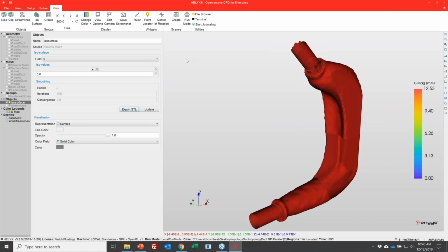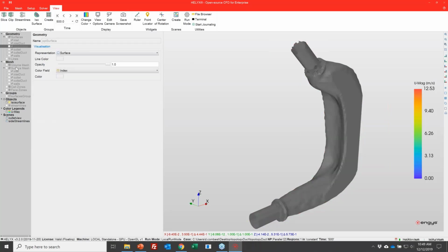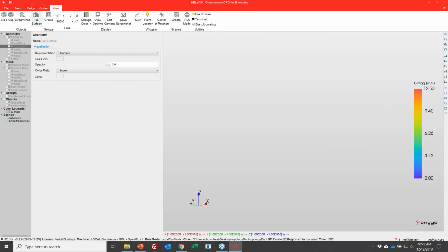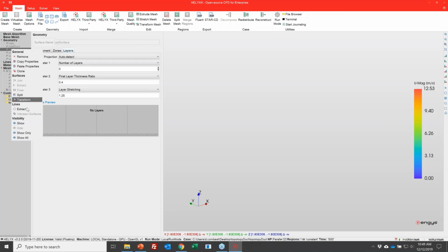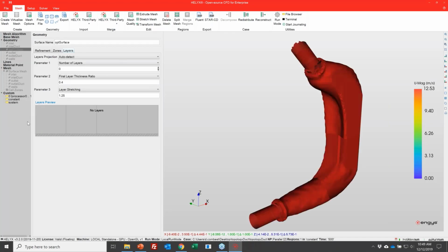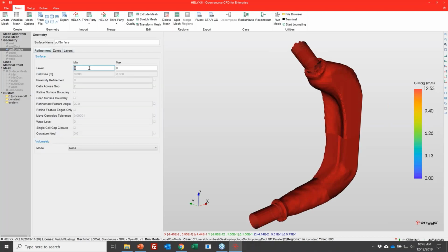There's several other parts of this whole process. One of the parts would be to bring this back in. So for this case, I've already brought it back in, but it hasn't been meshed. What we would do is we go all the way back to the meshing part, and we would re-import our optimal surface. There we would probably increase the refinements. We might even add layers.